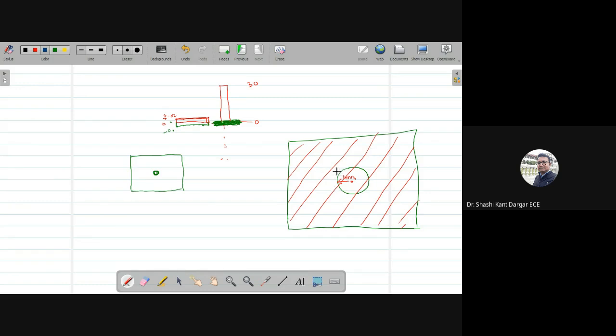So we will make a hole here, and for making the hole, we'll make a circle. It means the same cylinder here, and the cylinder should have a diameter more than the diameter of the rod. The rod was of 1 mm, so I want a little bit more than this. For the hole, I will take the radius, 1 is already there, so a little bit more I want. I will take 1.1 mm for this blue color hole, right?